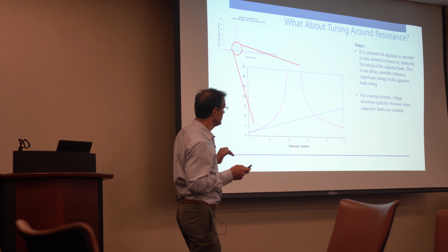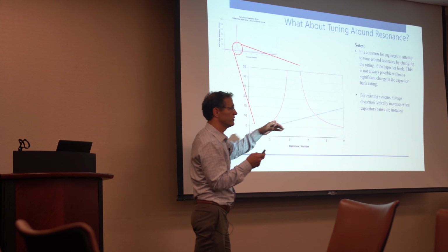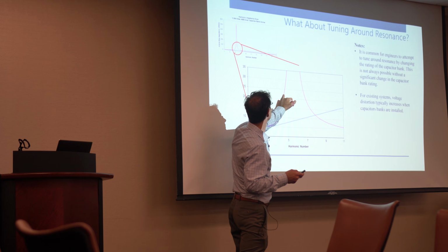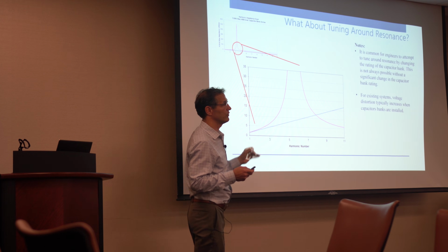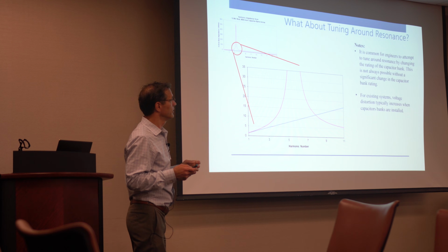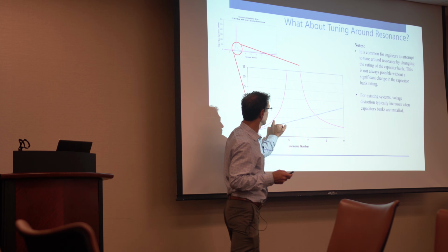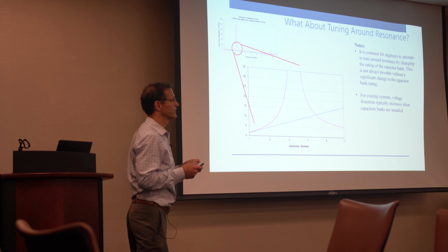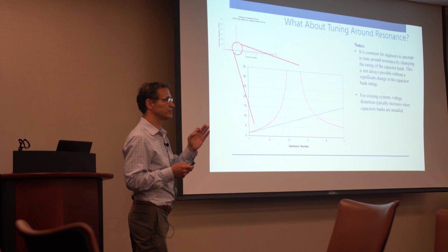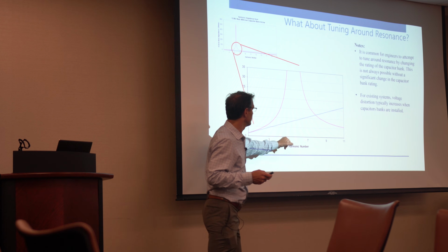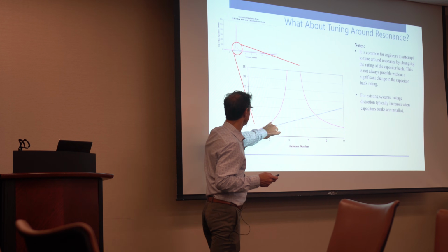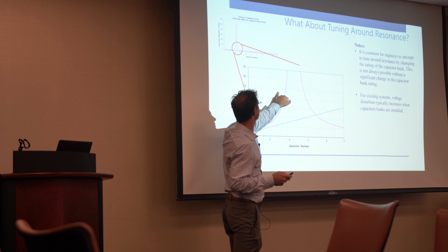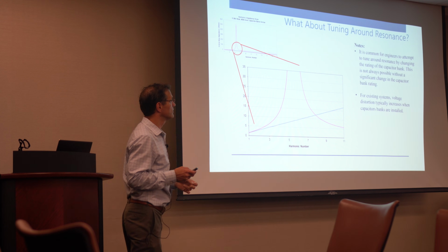But you can see here, this is our reference line. That's what it was before. And you can see at the fifth, come up, I'm maybe at 20 to 25 ohms. So there's a certain width to this resonance. You're not directly on resonance, but you still have increased the impedance of the network from this base value, what I would say 7.5 ohms, to some higher value, say 20 to 25 ohms.